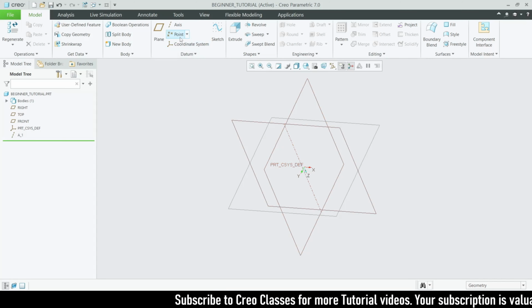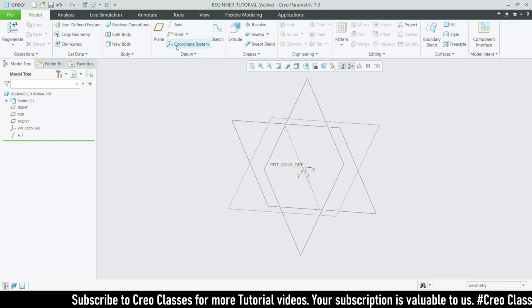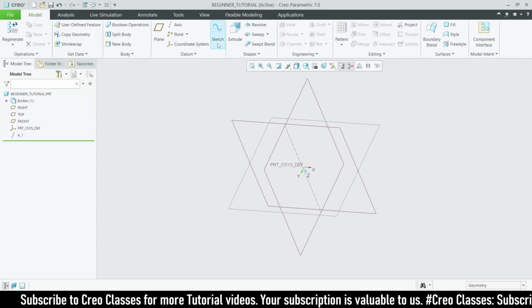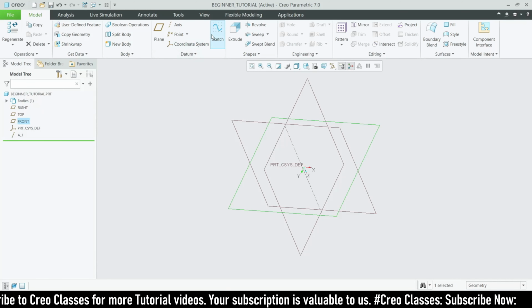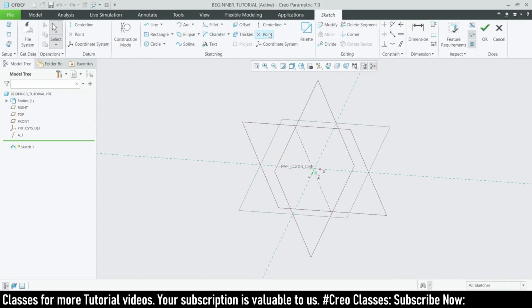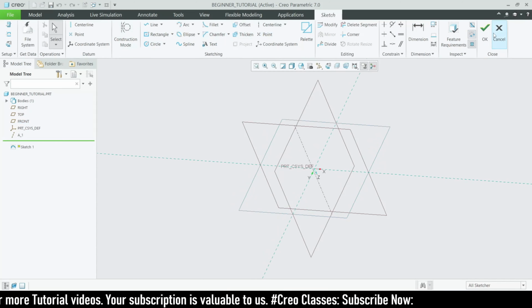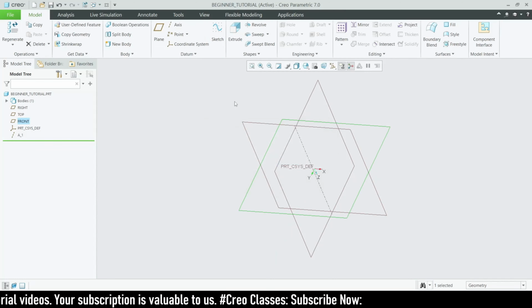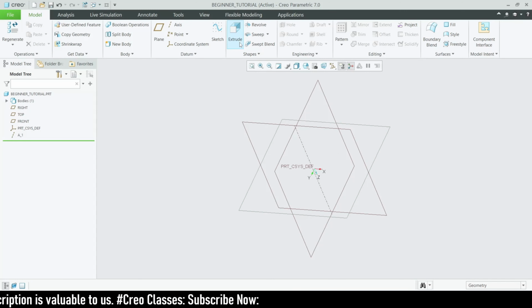Okay, point is similar to the tool which you have discussed in the previous video itself. Inside that sketch tool, you can also see the point option. The same point tool will be used here, but if we use the point tool on the sketch, it is only visible on the sketch. If we use the point tool here, it will be visible on the entire part.